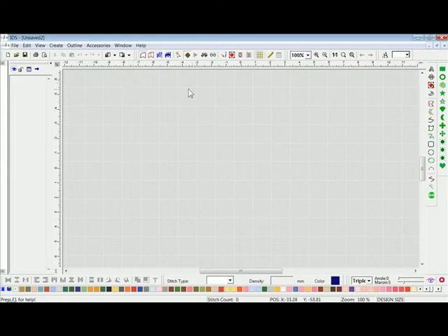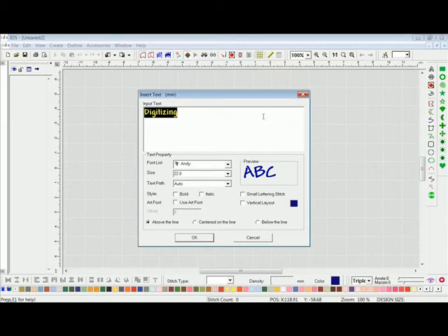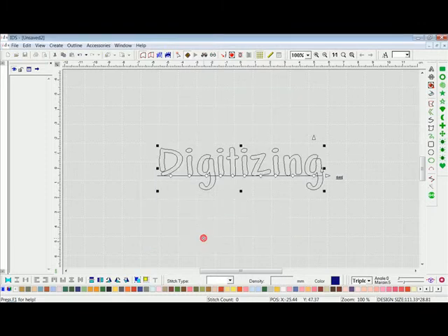To insert text on the right-hand side, we will click on the Insert Text icon, the first icon on the Create toolbar. When we left click on that, it will automatically input the last thing that we input for the insert text. We'll leave everything as is except for the text path itself. We're going to change the auto text path from auto to line. With this option here, once we press OK, our cursor will turn into a crosshair.